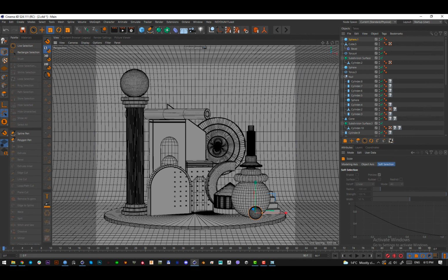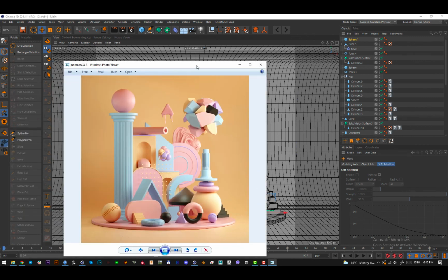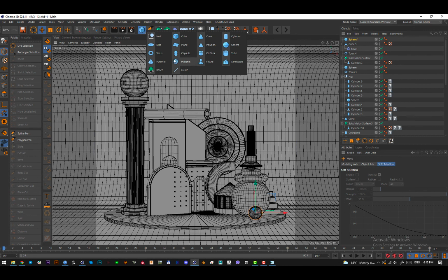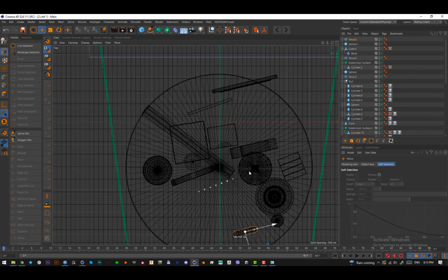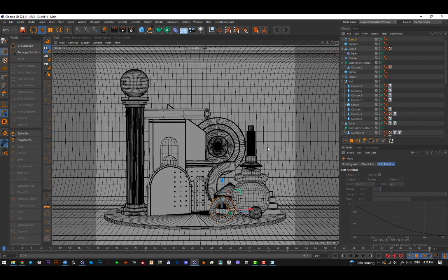Let's now add the next element, it's this one. So these are two toruses, so add a torus here, put it up, rotate it 90 degrees, rotate it like this, put it, increase, scale it up, and okay. Okay, now let's slice this torus, so here into the slice, use the slice. This is fine, let's increase the radius a bit.